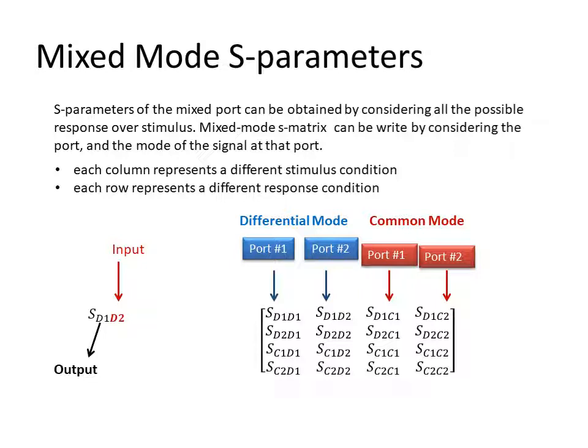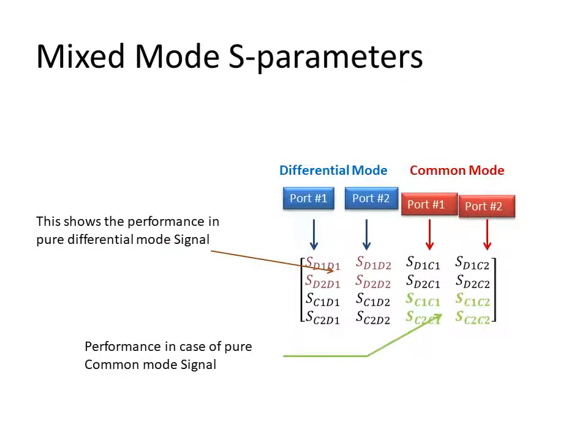Then how have we got the S matrix of a multi-port network, and we have studied what each element represents, and then how we analyze this S matrix and how we conclude by using it. So see this particular diagram. Actually this 4 cross 4 network is divided into four 2 cross 2 matrices.